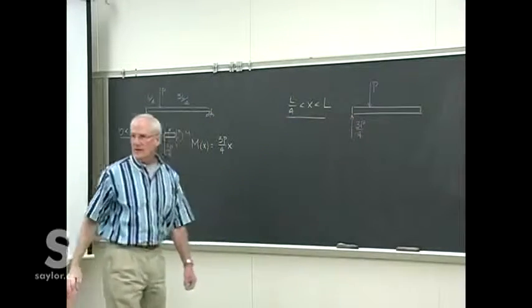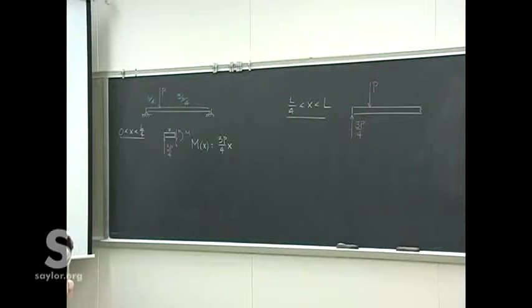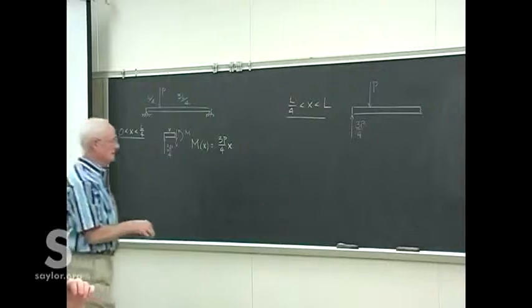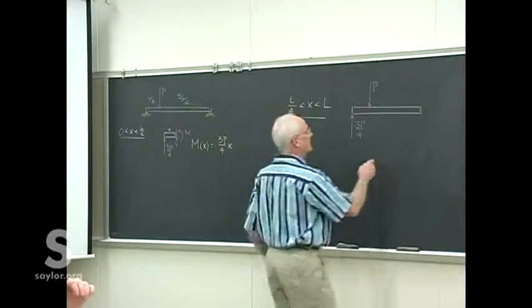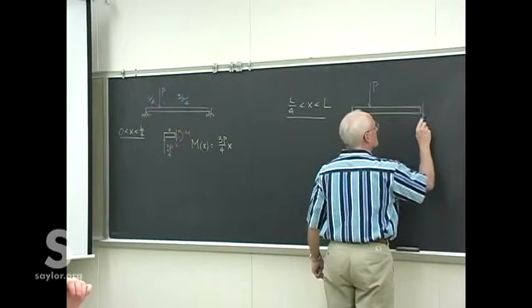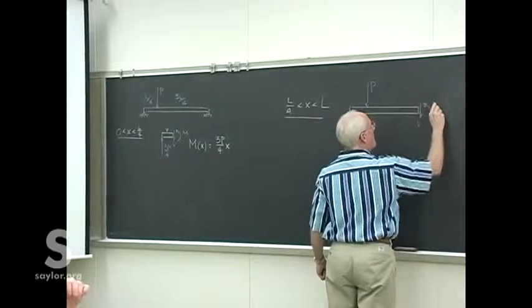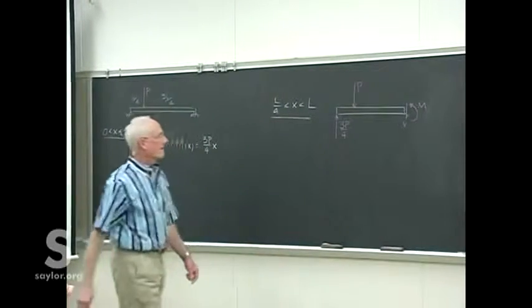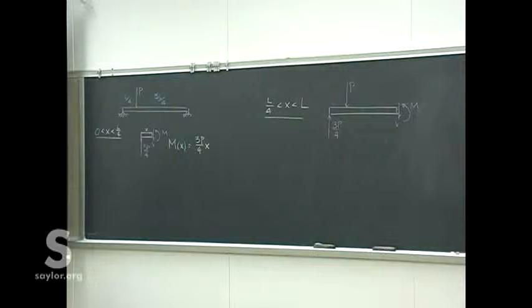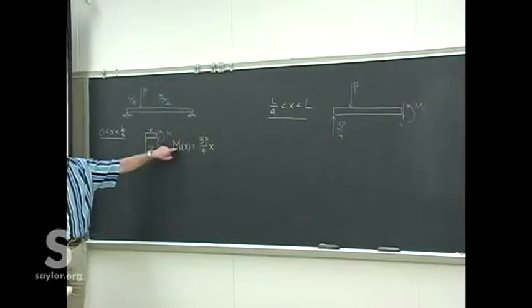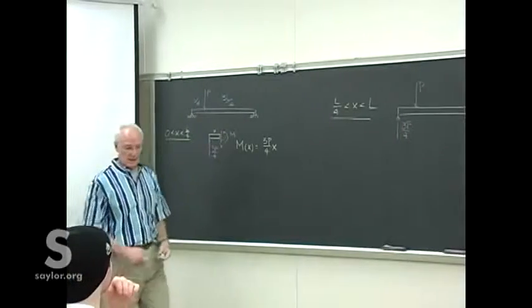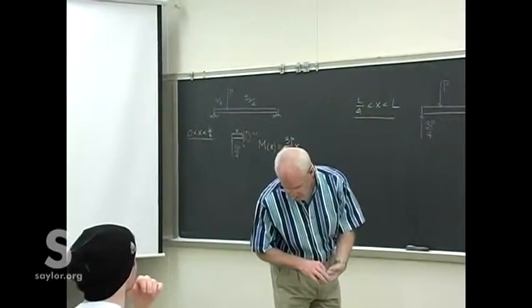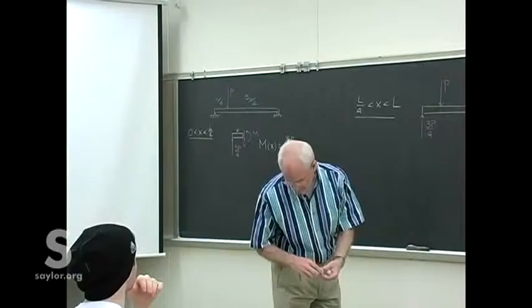And you could do it from the other side, but then things get a little bit tricky what X represents. You want X to always mean the same thing through all of these. So, start with that, integrate back twice and get the load curve, the deflection curve, the elastic curve.